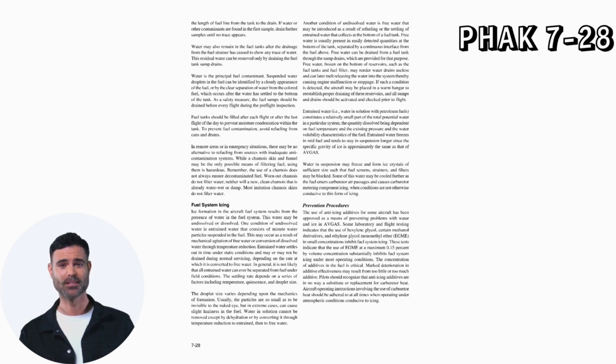If such a condition is detected, the aircraft may be placed in a warm hangar to re-establish proper draining of these reservoirs, and all sumps and drains should be activated and checked prior to flight. Dissolved water, i.e., water in solution with petroleum fuels, constitutes a relatively small part of the total potential water in a particular system, the quantity dissolved being dependent on fuel temperature and the existing pressure and the water solubility characteristics of the fuel.